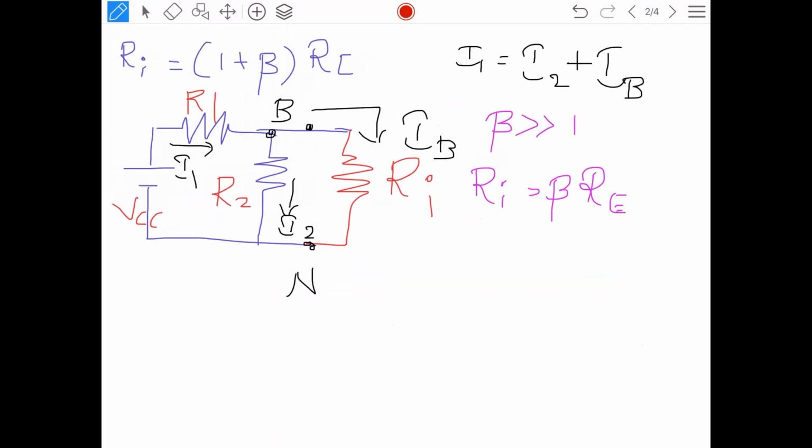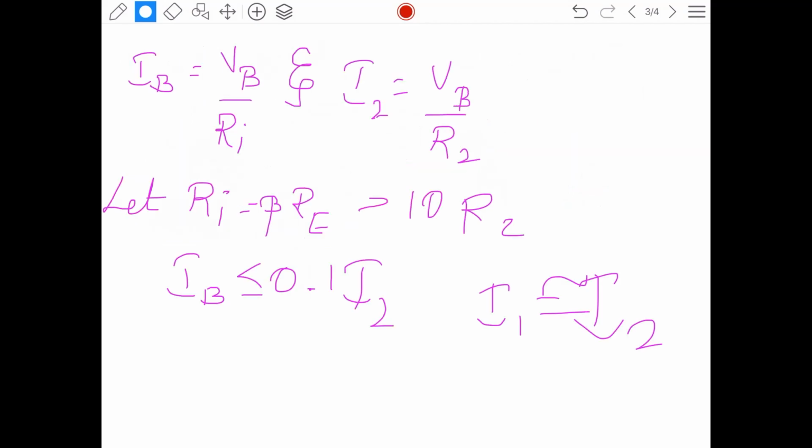Now let us go to the analysis at the voltage level. That is, we will be using the KVL equations as usual. Applying KVL to the circuit. Let's go to the circuit and see. VCC, I1 R1 plus I2 R2. Correct? See the loop here. VCC minus I1 R1 minus I2 R2 is equal to 0. Correct? So if I assume the currents are equal, then I can keep the current constant. How are we assuming the current equal? Here we have written it.